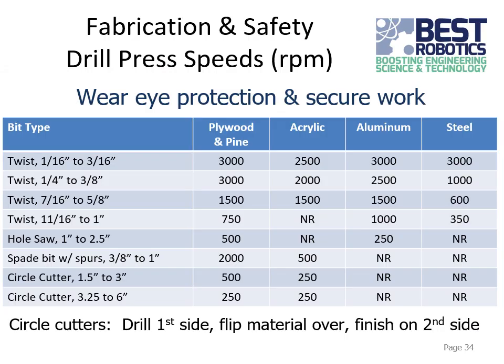And for drill presses, I've added this table here. This is just for reference, but you can find it online. A lot of drill presses, at least that I've seen, will have a little table like this for reference, either taped inside the cover or something like that, so that you always know how to use it. But in general, for smaller things and smaller drill bits, you can go faster. Bigger ones and hole saws, you need to go a lot slower with them.